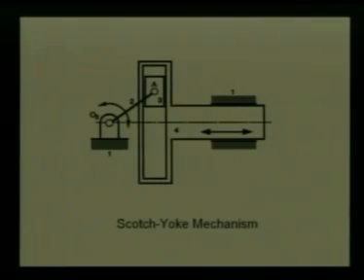It may be emphasized that continuous uniform rotary motion would have been translated into to and fro rectilinear oscillation by a slider crank mechanism that we have seen earlier. However, the to and fro oscillation of the piston of the slider in a slider crank mechanism is periodic but not purely harmonic. This periodic motion tends to be harmonic as the ratio of the connecting rod length to the crank radius keeps on increasing.